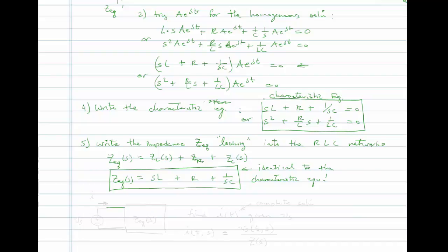All right. Now consider that I'm going to throw everything, my R, L, and C, into this box, and I'm going to call this Zeq. And I'm going to apply a voltage, Vs, across it, and there's going to be a current I that's going to flow. And the question is, what is the current I? After all, if we were solving this circuit last week, and I asked you to find the homogeneous response for this circuit, find I, you would be looking for the solution form of the current flowing through all of these. So here our task is to find I